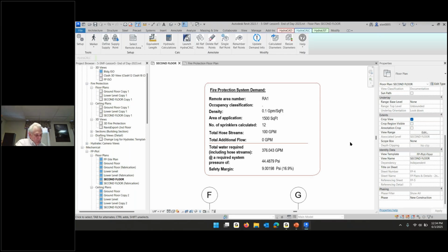But what I'm saying is, I think that would be worth spending a little effort to fix the programming so that it actually filled itself in correctly. We use two separate fields, one to calculate the value and another to carry the units so that you can have both there without having to convert it to text. It still keeps it as a numerical value by keeping the units as a separate field placed side by side within the family. Well, I think I'm probably going to go forward, Nathan, and make this be the new family.